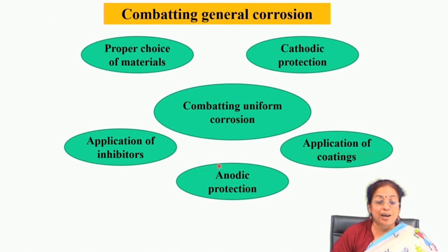So, you have to know the kind of corrosion that the component has undergone, and to know that you have to do different tests. For example, you can estimate the corrosion rate in that particular simulated environment by standard coupon testing, or you can do electrochemical testing like the electrochemical polarization technique for knowing the kinetics of the corrosion in that environment.